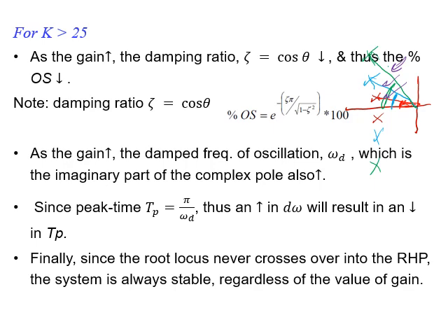If you remember, when we studied the transient response, we said that with zeta and omega n available, we can calculate any of the time response parameters. And they change as those parameters change. If zeta and omega n change, those times are going to change. That's how we can get some idea from the root locus on how the system will behave as the gain changes.